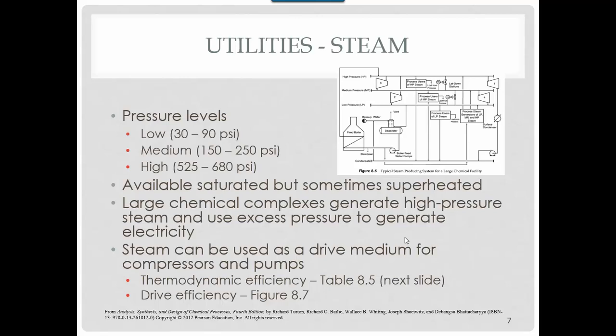Now, a lot of our utilities are about heat transfer needs. Steam is one of the biggest, most important utilities in most plants. Steam typically is going to be categorized as a high-pressure steam line or a low-pressure steam line, and those relate to temperature. So it's the quality of the steam, not quality as in the thermodynamic fraction that is vapor, but just how good the steam is, how much energy it has. So it's rated typically based on pressure level.